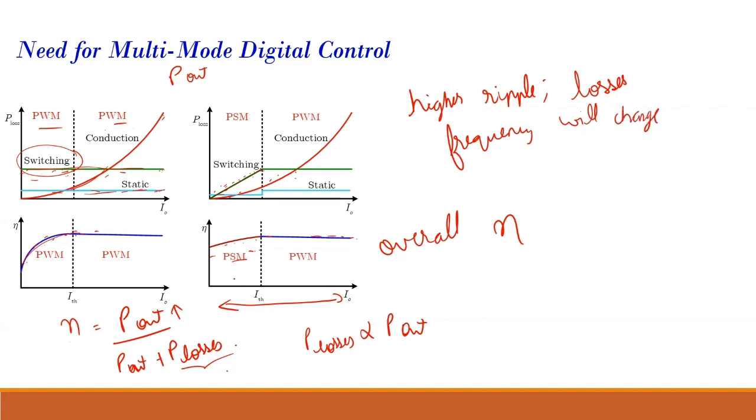At light load condition, your effective harmonics and THD will probably be lower in their impact. The power present in your harmonics would be less. But as you go to high load, that power will increase, so that should not exceed the limits.